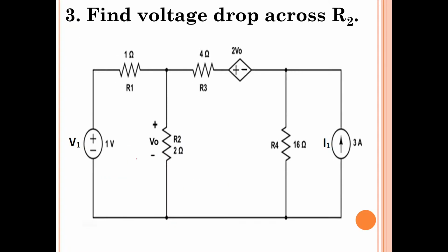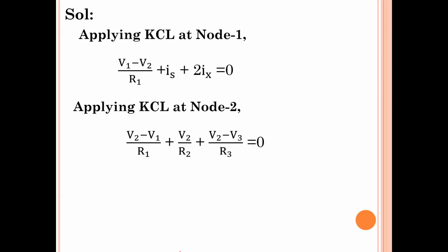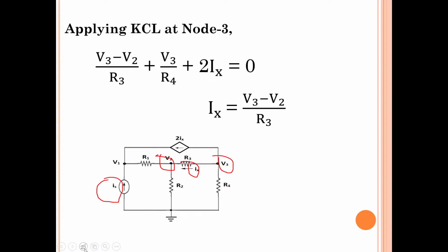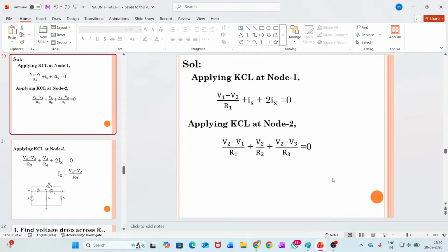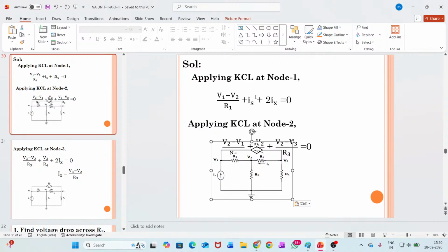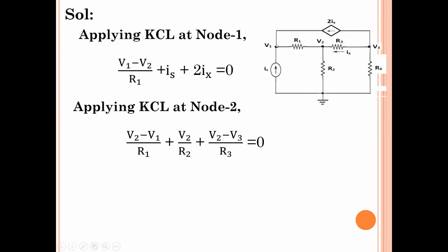So I can even modify this equation at node 1. I myself am not satisfied with the equation that I have written there. If you want, you can change it. Here, if you observe, both source currents are entering, so it's better if we assume the R1 current is also entering.